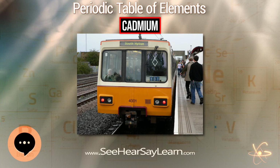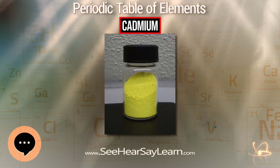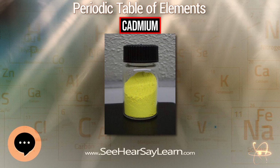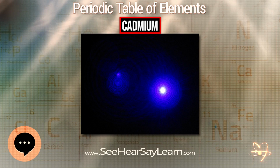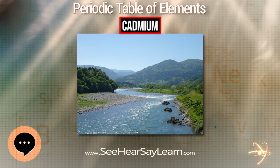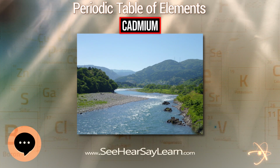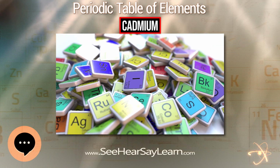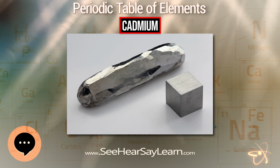Because these pigments are potentially toxic, users should use a barrier cream on the hands to prevent absorption through the skin, even though the amount of cadmium absorbed into the body through the skin is reported to be less than 1%. In PVC, cadmium was used as heat, light, and weathering stabilizers. Currently, cadmium stabilizers have been completely replaced with barium zinc, calcium zinc, and organotin stabilizers.